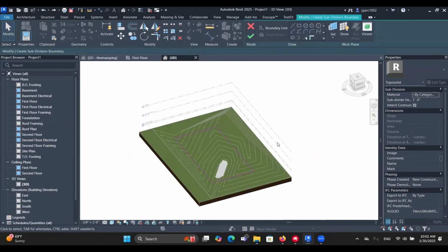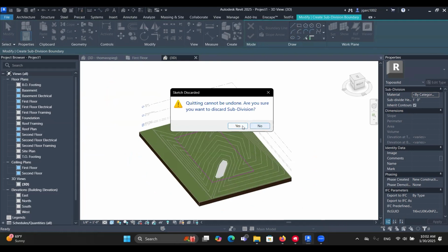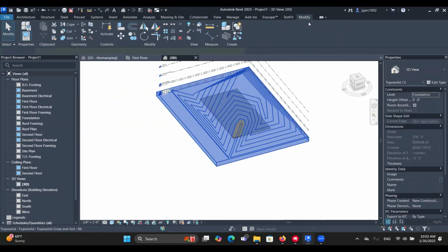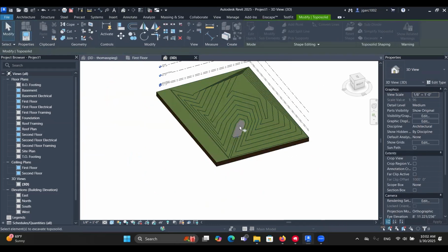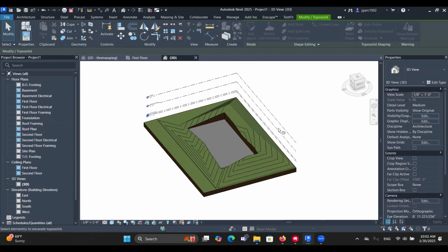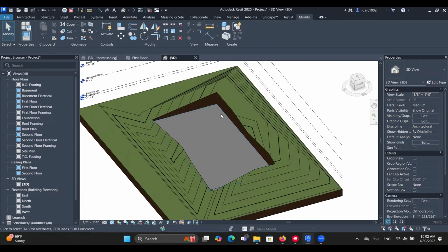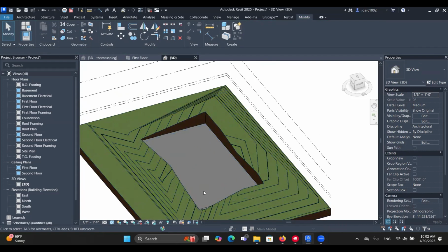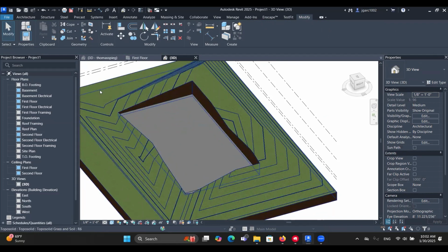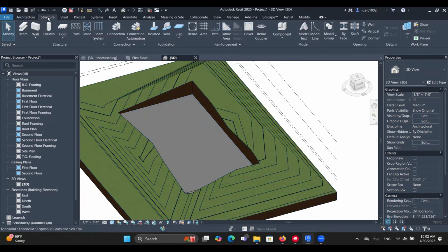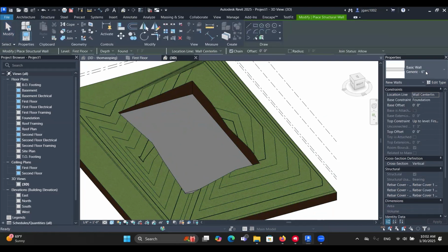But to teach you guys how to excavate really quick, excavate here, select this, and it excavates the project. So now you can actually work on it. You can actually put some walls into it, and say you want to do the foundation walls, the retention walls, architecture, you go to the part and structure wall.